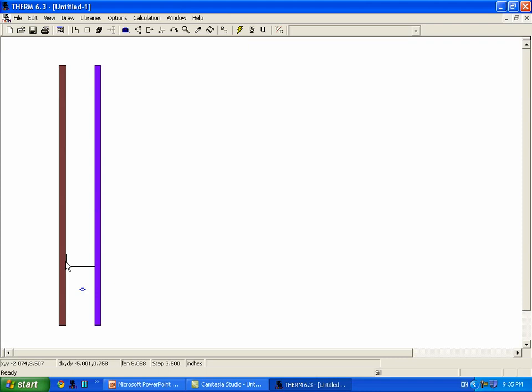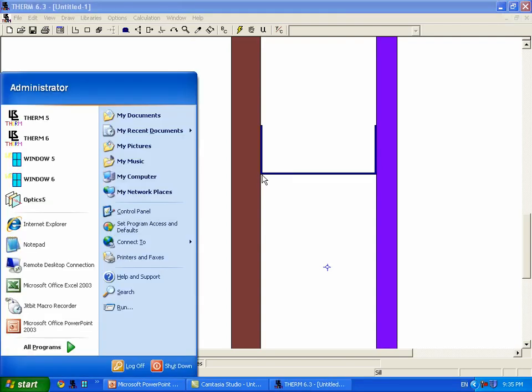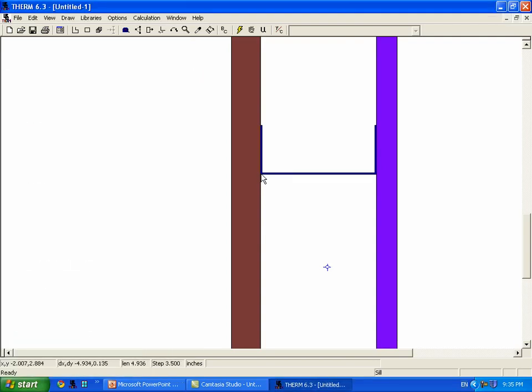So I'm going to go near this corner. Actually, I can zoom in and do it off screen. So we're near the corner here, and I type 16 up arrow, and then I do F2, which is draw locator. Accept.